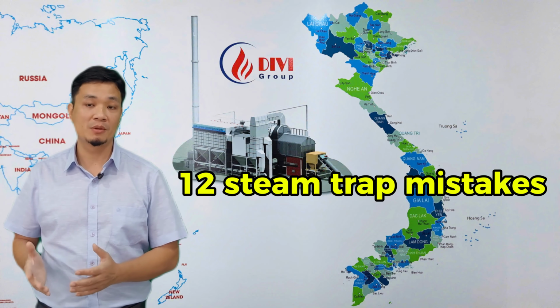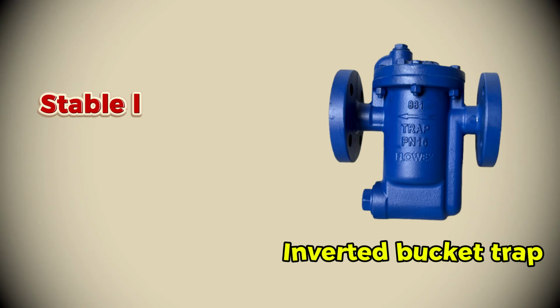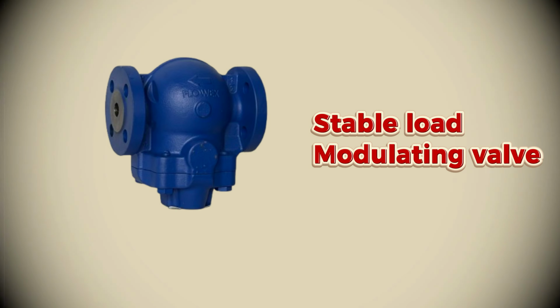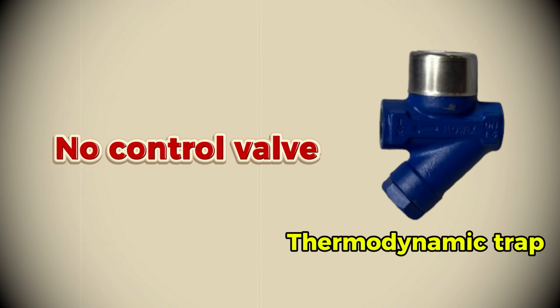Here are the 12 common mistakes related to steam traps. Mistake number 1. Choosing the wrong type of steam trap, as mentioned in previous videos. If the equipment has a stable load and uses a control valve to regulate steam, an inverted bucket steam trap should be used. If the load fluctuates and steam flow is modulated by a control valve, use a float steam trap combined with a thermostatic air vent. For discharge points without control valves, such as steam headers, steam lines, or end of line, use a thermodynamic trap.